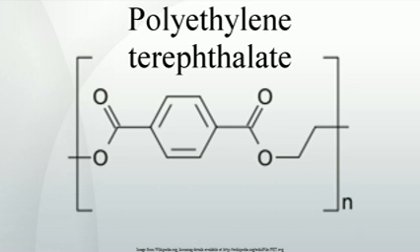Degradation. PET is subjected to various types of degradations during processing. The main degradations that can occur are hydrolytic, thermal and, probably most important, thermal oxidation. When PET degrades, several things happen: discoloration, chain scissions resulting in reduced molecular weight, formation of acetaldehyde, and crosslinks, gel, or fisheye formation. Discoloration is due to the formation of various chromophoric systems following prolonged thermal treatment at elevated temperatures. This becomes a problem when the optical requirements of the polymer are very high, such as in packaging applications. The thermal and thermoxidative degradation results in poor processability characteristics and performance of the material.